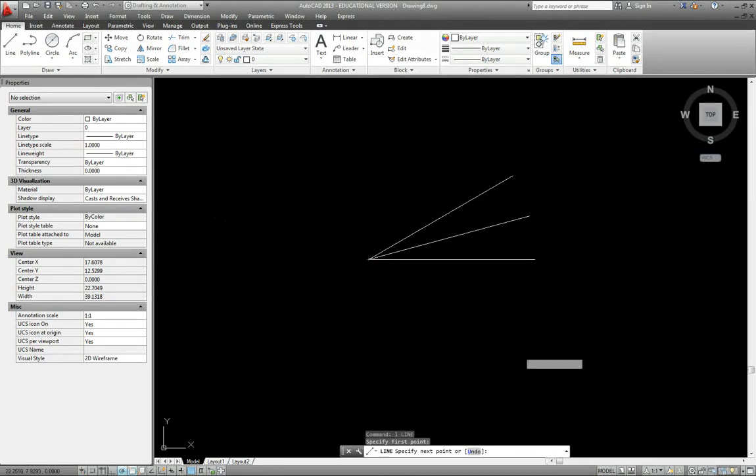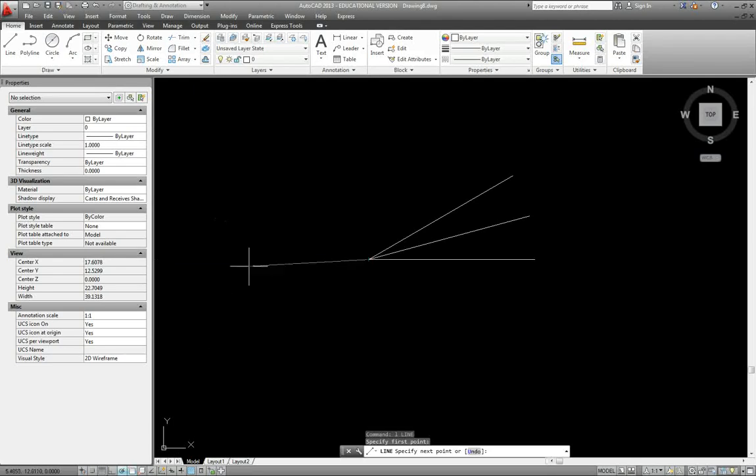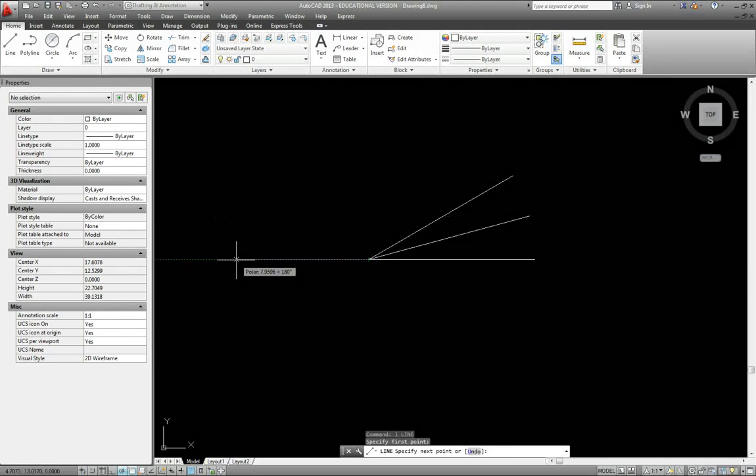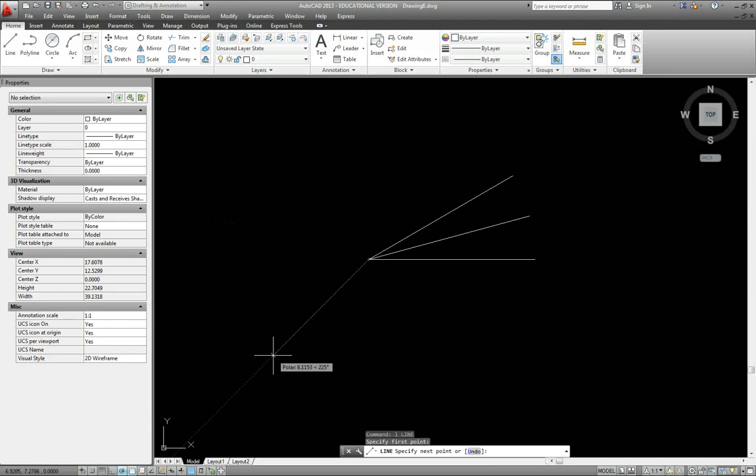Straight down is 270, and all the way back around is 360 or 0. So if I want to go 45 degrees below the horizontal here, that would be 180 plus 45. I could actually watch the tracking as it goes around, or I could shortcut, start off at 180 and then track down 195, 210, 225. There were 3 increments past the 180 where I was able to get to 45 degrees below the horizontal, and then I can just type in 10 and then enter.